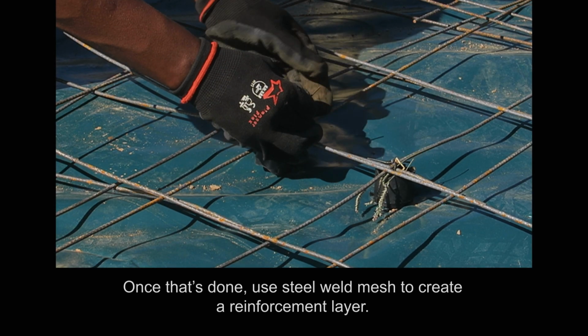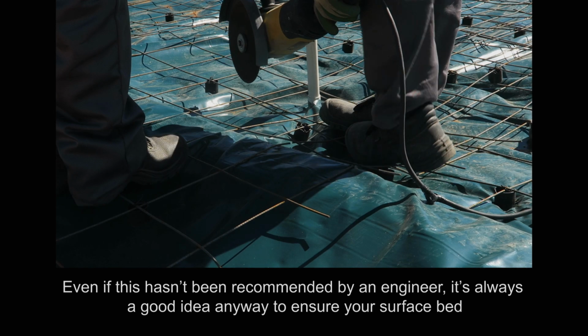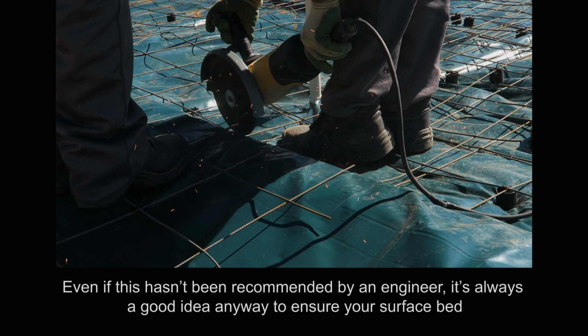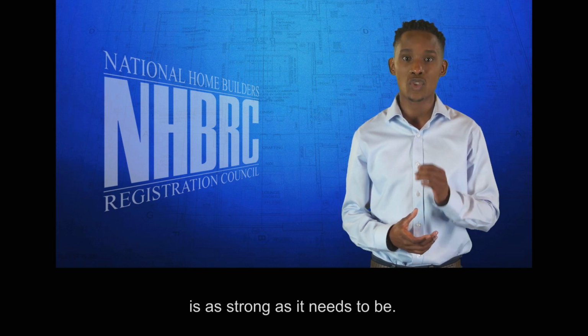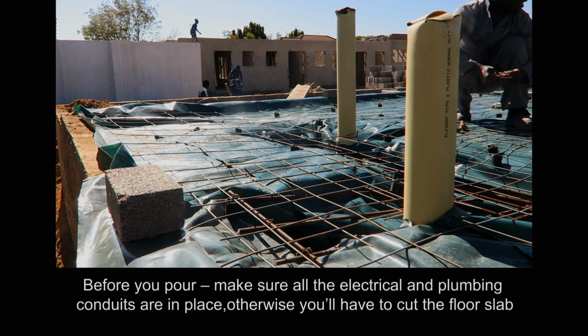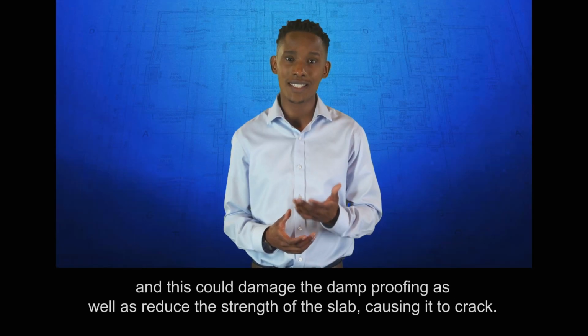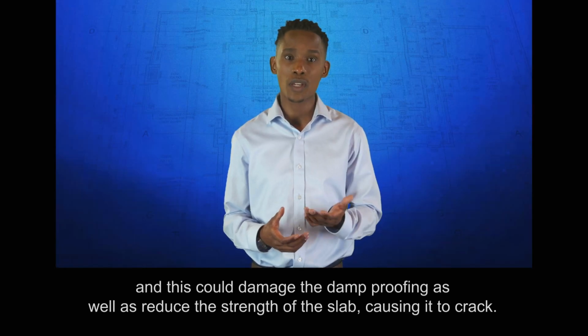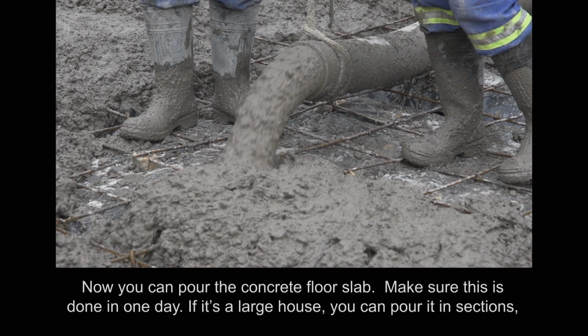Once that's done, use steel weld mesh to create a reinforcement layer. Even if this hasn't been recommended by an engineer, it's always a good idea anyway to ensure your surface bed is as strong as it needs to be. Before you pour, make sure all the electrical and plumbing conduits are in place, otherwise you'll have to cut the floor slab, and this could damage the damp proofing as well as reduce the strength of the slab, causing it to crack. Now you can pour the concrete floor slab.